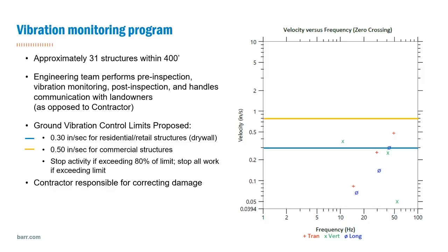As part of the vibration monitoring program, we ended up with about 31 structures within 400 feet. We sent up an engineering team that has done a lot of pre-construction inspections in the past, and we would go through each of those structures as I discussed and document everything. And then we set up vibration monitoring, post-inspection, and constant communication with the homeowners as they needed it.